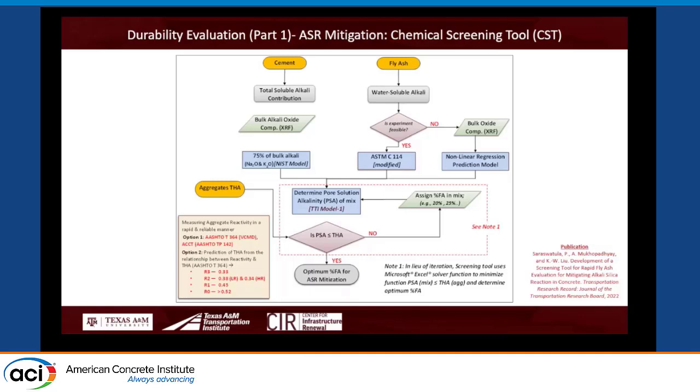See, the extraction technique is laborious and very few people do that. That can be used for validation purposes. So what I did is, see the cement, and you know SCM contributes soluble alkali. At this time, it is considered inert. That's not a good assumption. Some of the SCM contribute soluble alkali and enhance pore solution alkalinity.